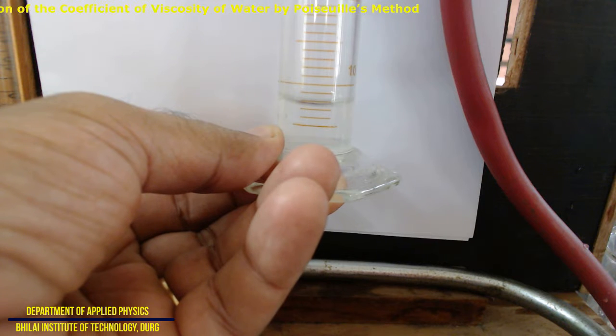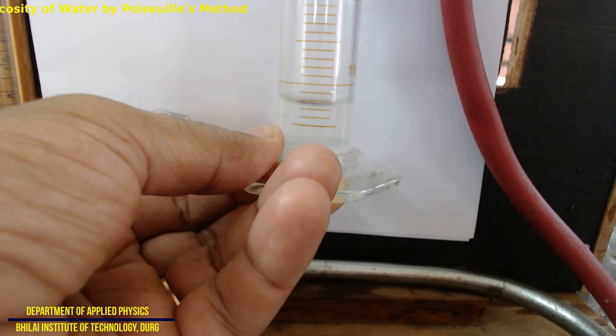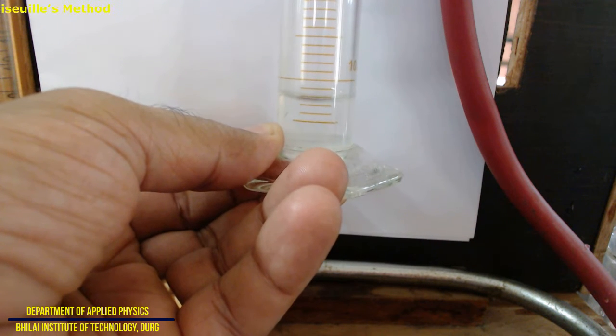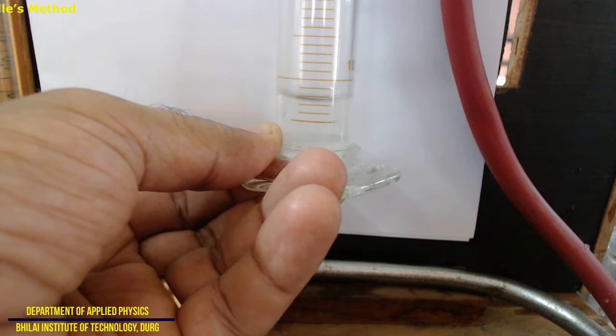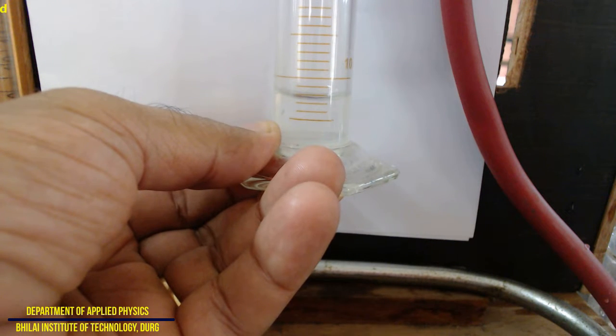Yes, now you can see the water collected in 1 minute, that is 60 seconds. It is 5 ml, 6 ml and 7 ml. 8 ml, approximately 8 ml, but the 8 ml mark has not been crossed. So we are going to take the lower meniscus, and obviously we are going to take the reading, which is 7 ml. 7 ml water has been collected. So that is the value of V, volume collected 7 ml, time T is equal to 60 seconds.